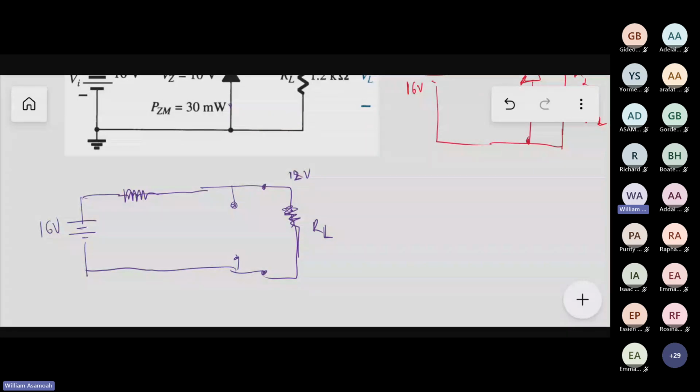That means that 12 volts is sufficient to bias a Zener diode. But the Zener diode has a behavior that when the voltage gets to 10 volts, the Zener diode can bias. Then it starts working. And I've told you that when the Zener diode biases and starts working, the voltage 10 stays there. Even if you put 20 at the input, it will still stay at 10. It stays there because it has broken down, so it can't do anything again. It can only function there.